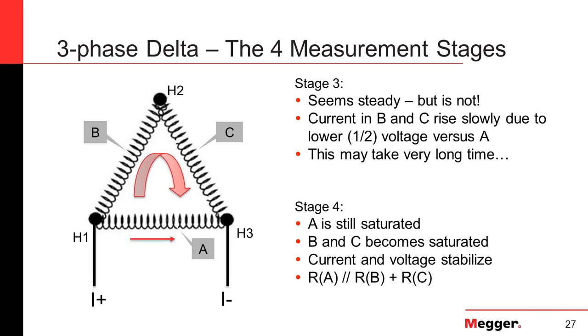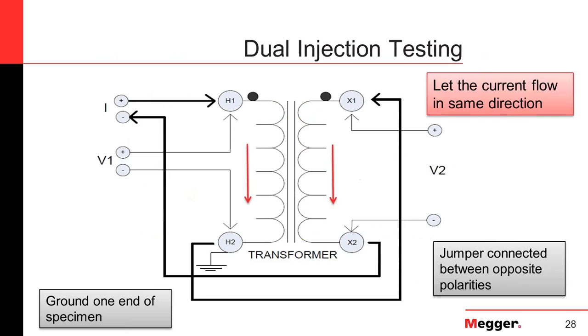It is under these conditions that we typically want either higher voltage, or what will help us are some higher currents, at least reaching the 1% or 2% plateau. So if we take all of these examples and we look here in the dual, the reason we do so isn't just to saturate the core, but in this case, we perform 2 tests at one time. Because winding resistance takes so long, doing 2 tests or 3 tests or 4 tests at one time is the optimum way from an efficiency perspective.